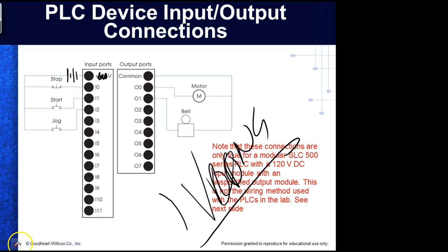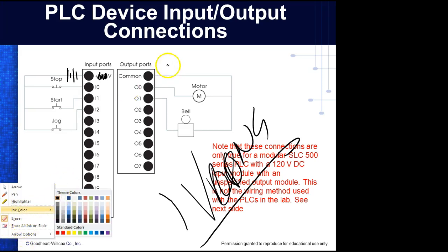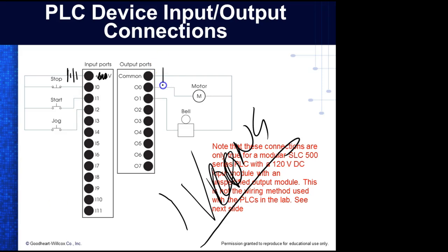So on the 1100s, you'll just draw it like what? Just draw it through the line, just like that. And of course, what are our batteries? Our DCs are 24 volt. But putting that up there, odds are that won't be a motor. Odds are it'll be a relay that controls the motor. Are we okay? So y'all just modify y'all's lab books a little bit according to whichever PLC that you're on. Are we okay?